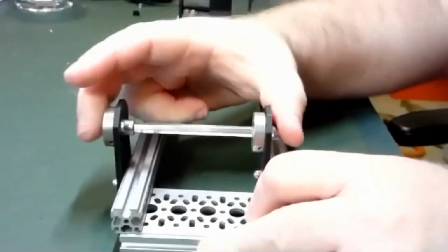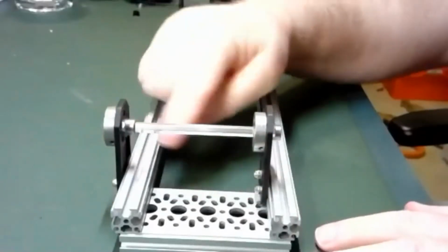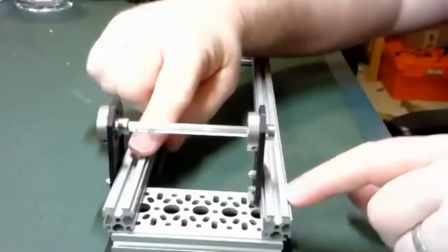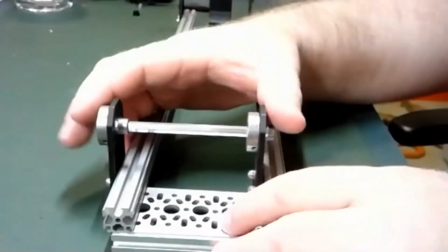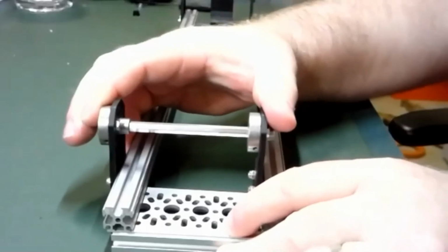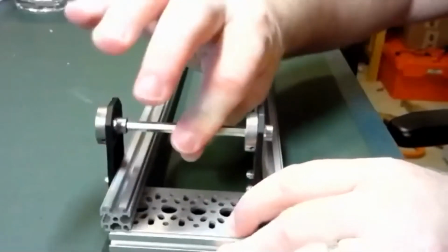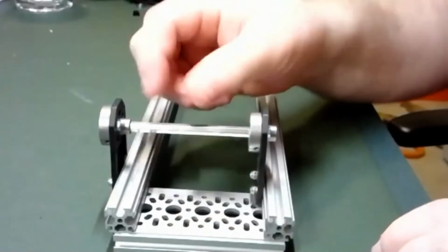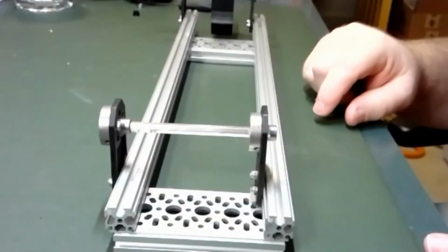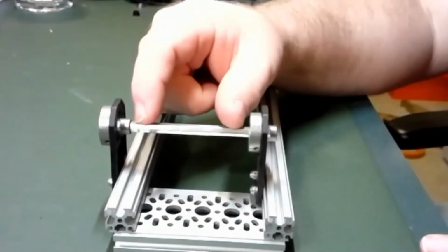What you've done is you've made a nice little box structure here, right? You have things fixed here and things fixed here, at right angles with each other. So you have this really strong structure that's going to hold the axles parallel to the ground and so on. That becomes really handy for your wheels, and it's really good for Mecanum wheels because you know they're going to stay flat on the ground.